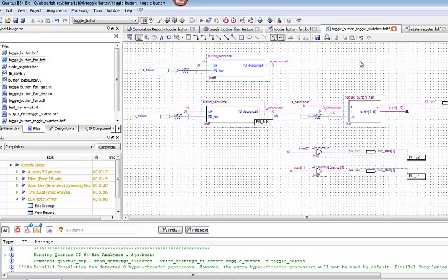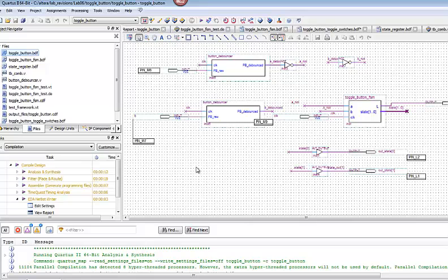Alternatively, you can use your push button switches. With your push button switches, we know they are low true, and so we want to add some inverters. Coming out of our debounce switches, we need to add some inverters. So here we have A0 coming out of our A debounce circuit, and here we have our B0 coming out of our B debounce circuit. Now, don't try to run ModelSim for this level.